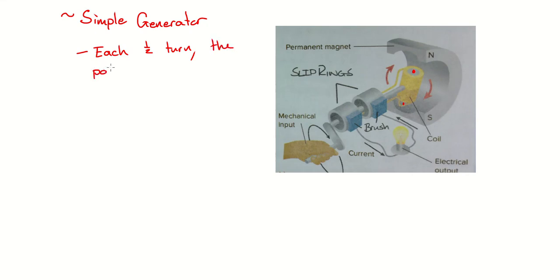And when I say this, I'm going to hold off before I write any more. When I say the poles change, it's obviously not the magnet's poles, because what sort of magnet do we have there? Permanent. Like that's just stuck there. It's inside of whatever. When I say the poles change, if this is side 1, right now it's on north, right? Half a turn away, where is it? South. So I see that those poles are changing with regard to the solenoid here.